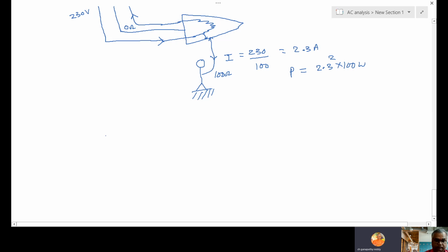Now some more concepts. Should an AC source have a plus minus or not? This AC source plus minus, we should have compulsory. Some students think that AC source means sine wave. So sine wave is always positive, negative, positive, negative. So positive, negative continuously changing. There is no sense of showing plus minus. But the correct answer is we have to show plus minus.